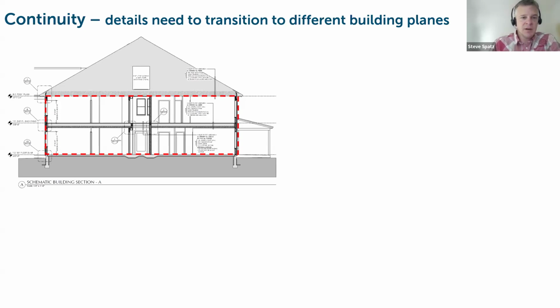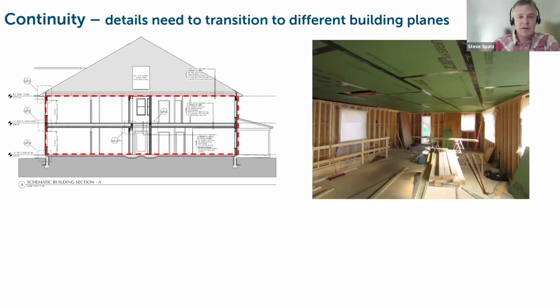And in this example here, one of the critical things to be mindful of is that if you're using your sheathing layer as your air barrier, your sheathing layer being the outboard most layer before the siding of the building, you need to understand how you're going to carry that continuity to the inside of the building when you have an open flat attic assembly above it.